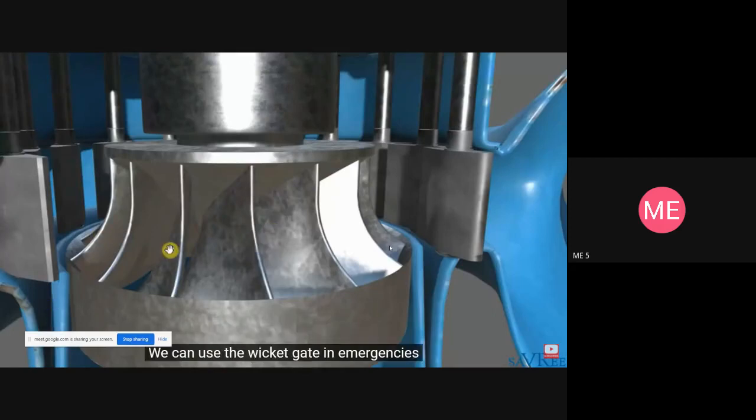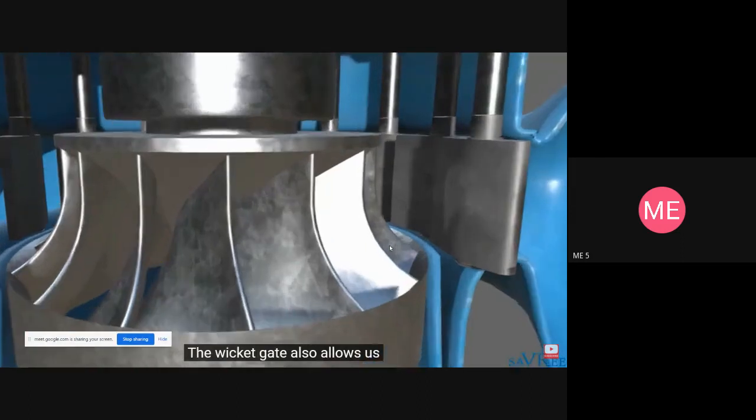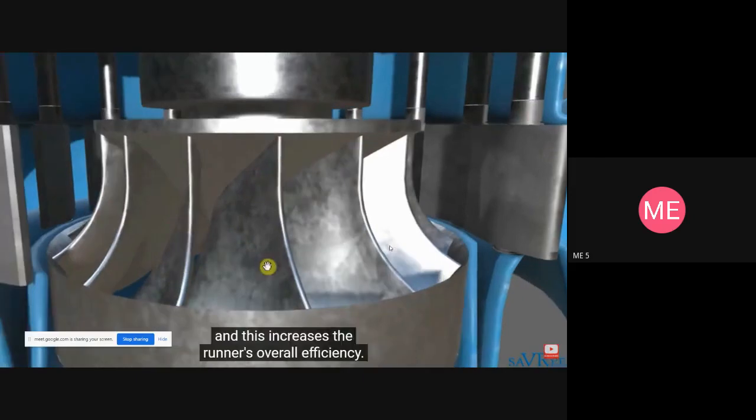We can use the wicket gate in an emergency to shut off the water flow, although it's more generally used for flow control. The wicket gate also allows us to angle the water as it enters the runner, and this increases the runner's overall efficiency.